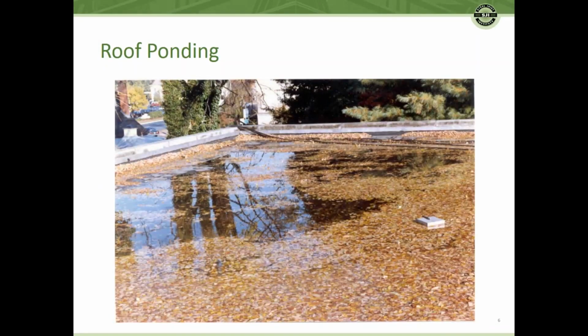This is simply a slide that I took a few years ago. It's just standing water, and there's a bunch of leaves on top, and I thought to myself, boy, we're really asking for a ponding stability problem here, because very likely the roof drains are not working, and I didn't see any secondary drainage system. But as far as I know, on that particular building, nothing bad happened, but let's hope that was the case. But ponding, as we're talking about, is for stability of the roof. It's a stiffness requirement mainly, and a strength requirement.